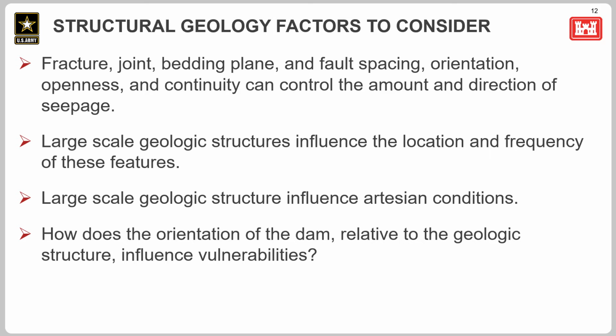Large-scale geologic structures could influence the location and the frequency of these fractures, joints, and bedding planes, and also could influence what the groundwater conditions are, whether there are pressurized water conditions. Also think about the orientation of the dam relative to these larger geologic structures and whether that orientation makes the structure more vulnerable to internal erosion or not.